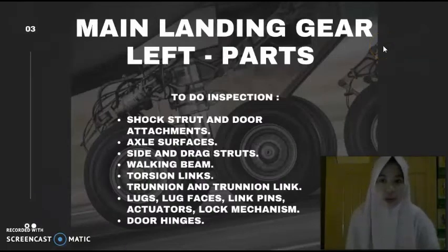As you remember, we are concerned with main landing gear left parts, and to do inspection there are shock strut and door attachments, axle surfaces, side and drag struts, walking beam, torsion links, trunnion and trunnion link, lugs, lug faces, link pins, actuators, lock mechanism, door hinges.